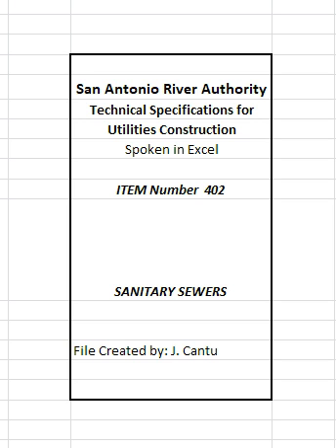A. When flexible pipe is used, select initial backfill or approved optional select initial backfill in accordance with item number 400, Excavation, trenching and backfilling, shall be mandatory and is required in the bedding zone and in the initial backfill zone. B. Deflection test.